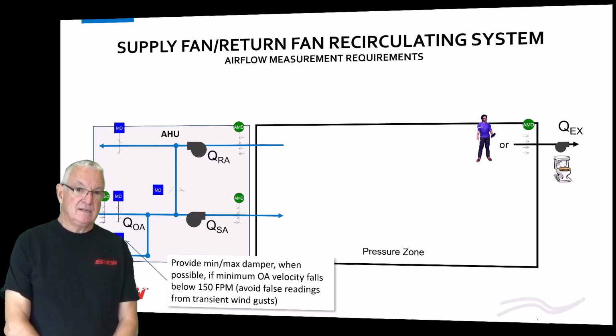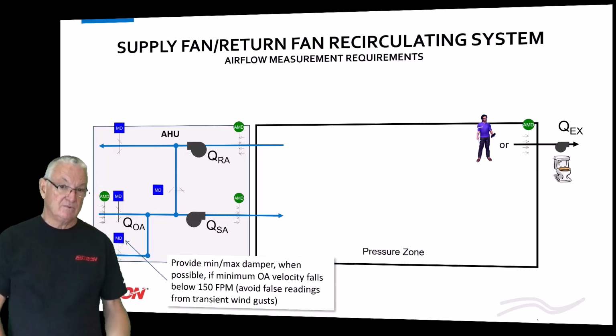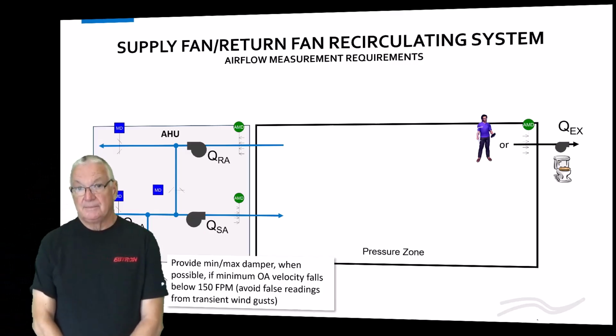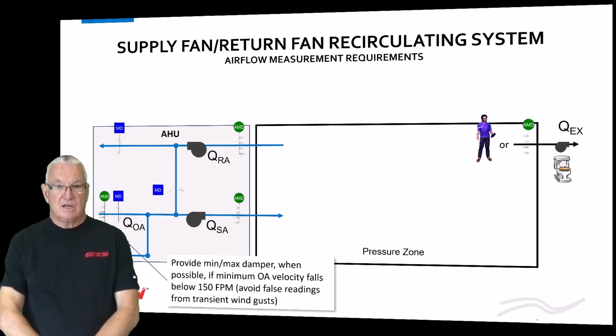Okay, and in certain environments, you get accumulation of material on that intake that accumulates on the sensors, and it causes some problems. That problem goes away typically with maintained moisture eliminating filters or air filters. Okay, I actually like washable air filters. But at any rate, think about this lower limit.